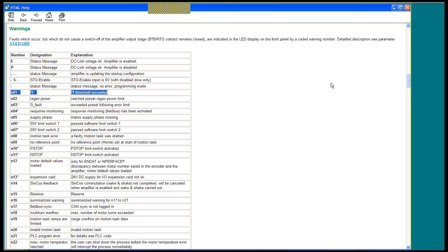It causes things such as position error on the machine, or the higher level control may trip out due to the fact that the motor doesn't have full power to move the load around. If the condition is corrected, such as the demand for the current goes away, the warning would disappear from the front of the drive. So the N01 would no longer be flashing and the current would no longer be in limit.